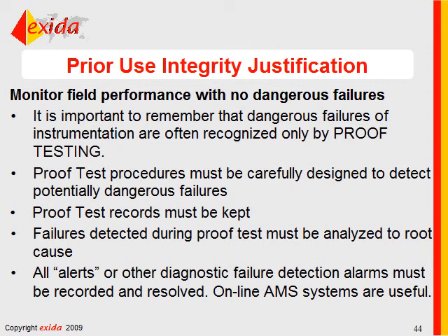So what do you got to do here? You got to do proof tests. You got to have good proof tests. You got to keep records. And when you get failures, you got to analyze them. You also have to pay attention to those automatic diagnostics. When you get an alert or some kind of other diagnostic alarm, you have to go resolve the issue.